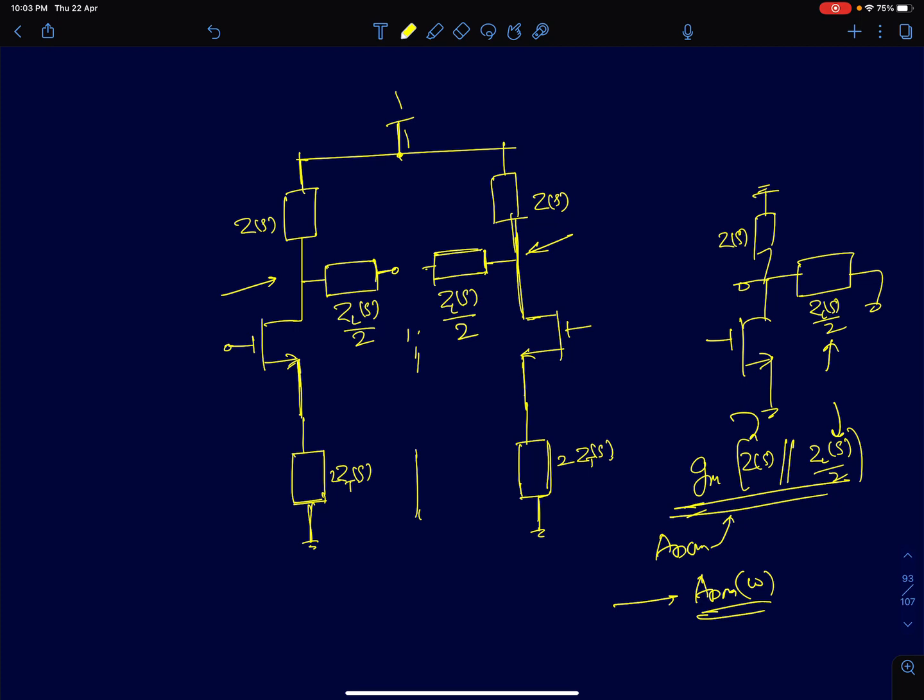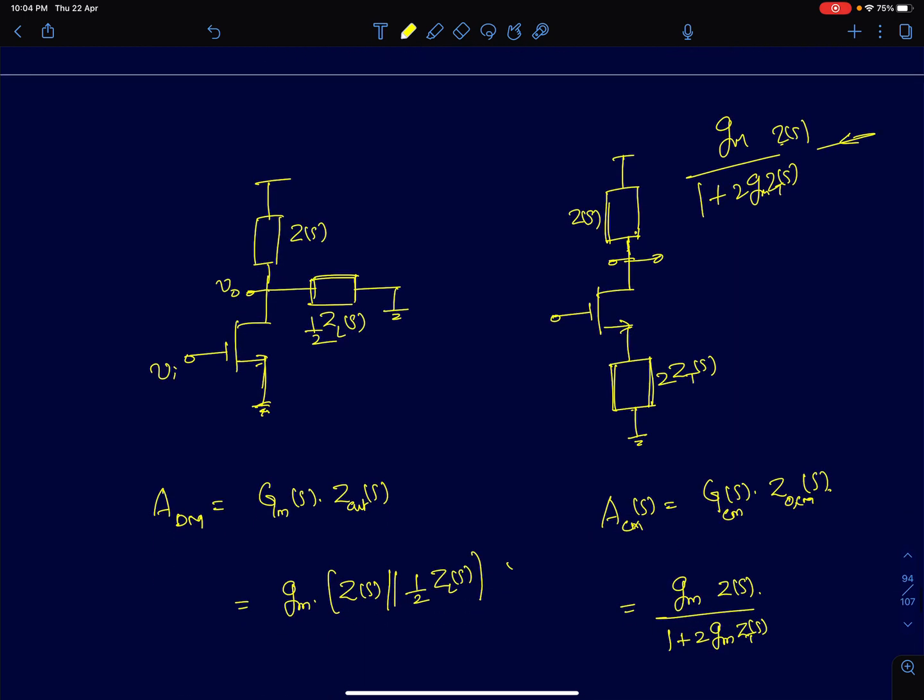Of course, if let's say the impedance is slightly complicated, we connect some other impedance here, then yes, it will have some dependence because there is some path to the ground. But otherwise, if we connect a floating impedance between these two terminals, that will have no impact on the common mode gain of a circuit, because in the common mode half circuit we are opening this node, so the current flowing through this is 0, so the voltage across this is 0. So I can simply ignore that and show the common mode half circuit which is shown here.